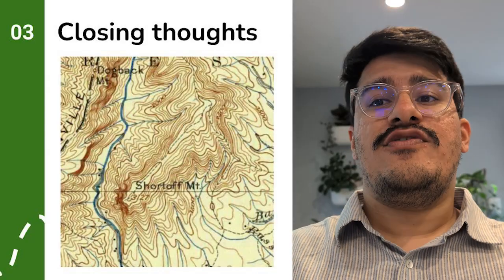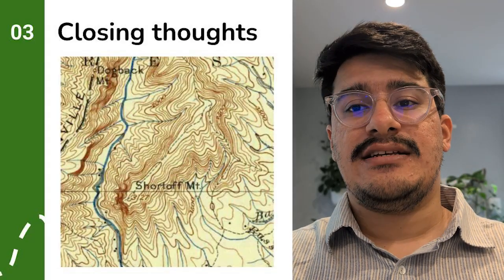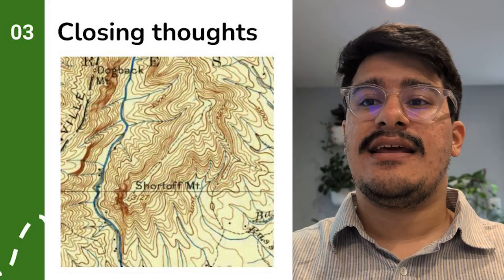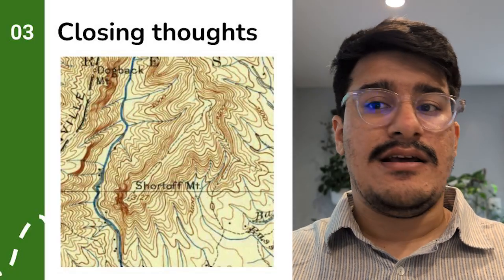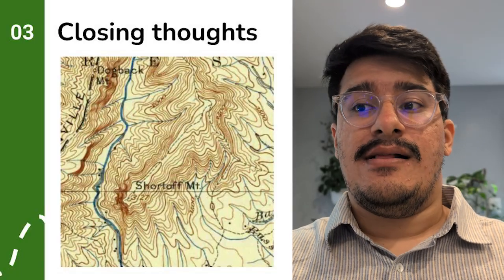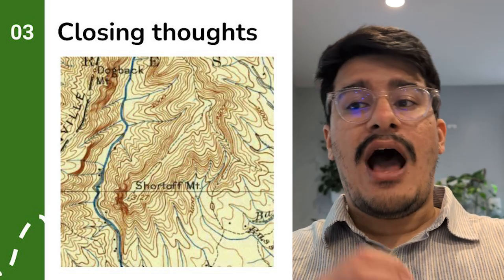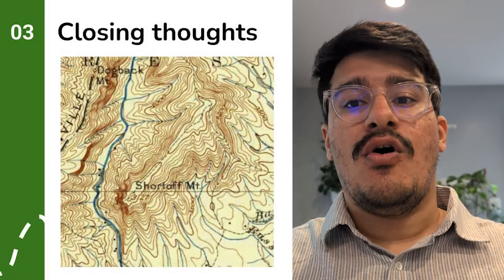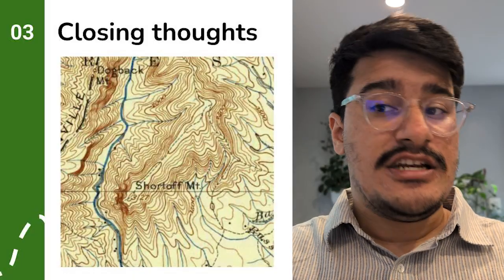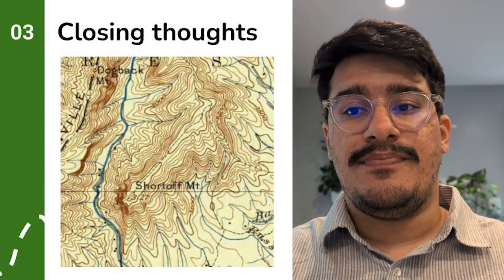In short, if you see someone just taking the highest and lowest elevation of a big site and dividing it to get a percent, be very skeptical. This is almost always an oversimplification, if not an outright attempt to bypass laws and regulations. A legitimate slope analysis will either what?